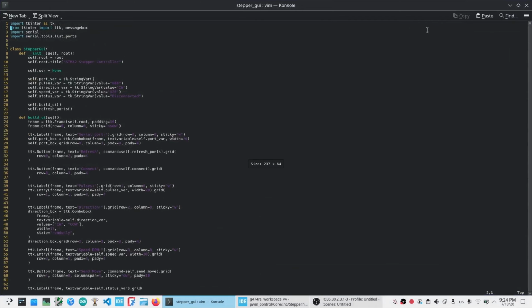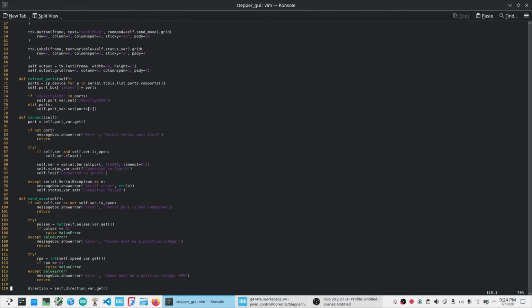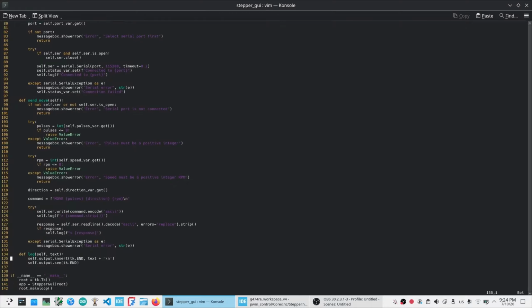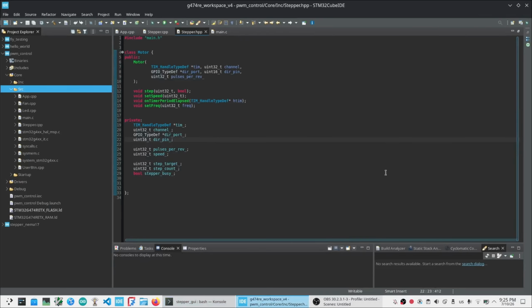So the raw serial text "move 1600 CW 70" is converted into internal values: pulses, direction, and speed. Then the firmware calls the motor control code. This is much better than using blocking scan, because the firmware does not stop forever waiting for input. It can continue checking buttons, handling the motor, and processing other tasks.